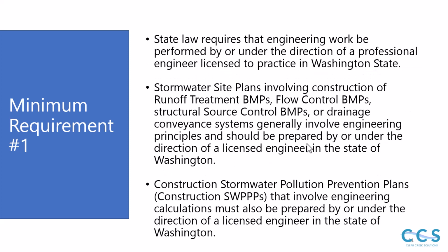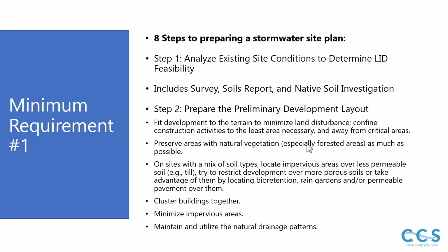And then state law requires that engineering work be performed by or under the direction of a professional engineer licensed to practice in the state of Washington, in this case. And the stormwater site plans involving construction of runoff treatment BMPs, best management practices, flow control, source control, or drainage conveyance systems generally involve engineering principles and should be prepared by a licensed engineer. And then construction stormwater pollution prevention plans, or SWPPP, that involve engineering calculations must also be prepared by or under the direction of a licensed engineer.